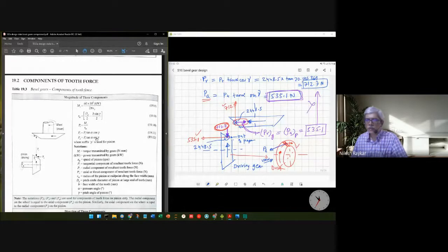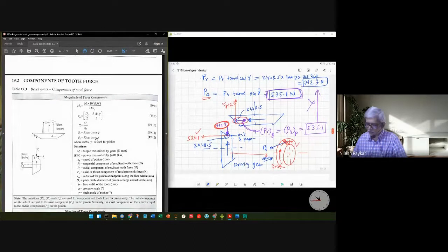As we know, in the spur gear and helical gear, the strength of the gear is expressed in terms of tangential force acting on the gear. So note that the tangential force that we did in the force analysis, what we did just now, is used to calculate the reactions on the bearings or the shaft calculation, the load coming on the shaft and so on. They are not used for the tooth force calculation or tooth strength calculation. Why it is so, we'll come to know when we derive that particular expression.